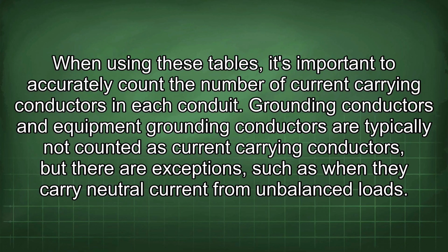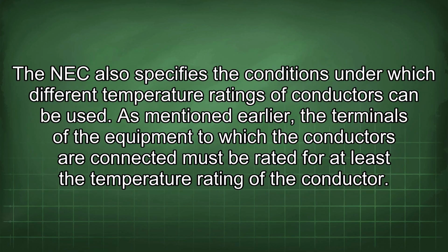Grounding conductors and equipment grounding conductors are typically not counted as current carrying conductors, but there are exceptions, such as when they carry neutral current from unbalanced loads. The NEC also specifies the conditions under which different temperature ratings of conductors can be used.